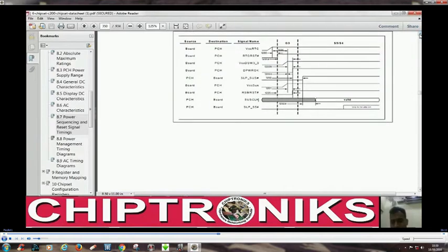But in S3 stage, what do we call the S3 stage? S3 stage is called suspend to RAM, right? That is, the context is saved in RAM. When your notebook motherboard is in S3 stage, the context is saved in RAM. But in S3 stage, the clock generator has not turned on.